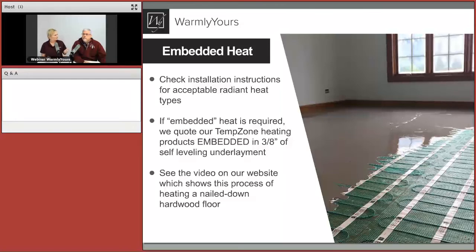The heating element is about what, one? Well, it's about a 16th of an inch, but the end cap is a little bit thicker, and the factory splice is a little bit thicker. But the thinner that base is, the more you're going to get the heat just going into the air. So you may not get the floor temperatures you're looking for. Also, it might stripe on you. If you get too close to the wire, you may actually see a warmer spot here, colder, warmer, colder, warmer. So by giving 3/8 of an inch, you're creating a nice heat bed, which spreads the heat out, keeps it in the floor a little bit more than just letting it go out into the atmosphere.